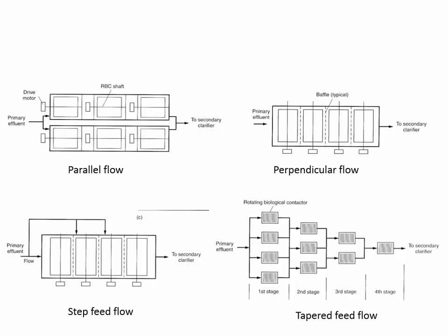So that's the counterintuitive thing about tapered feed. You might think that it would spend the most time in the 4th stage, because that's when the concentration is low and the kinetics are unfavorable since the concentration is low. But actually it's spending very little time there.